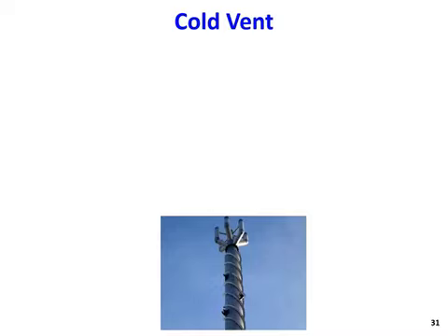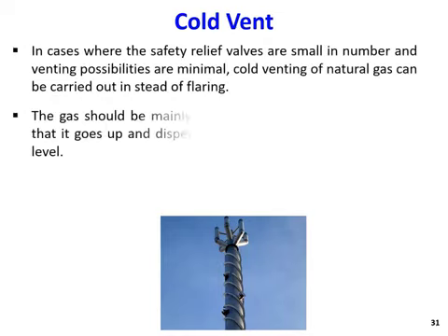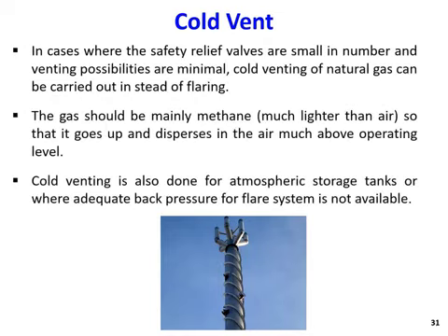So cold vent, as I already explained, can be used in cases where we don't need to burn the vent gas. I mean, in the flare, we don't need to burn it. We can just release it as it is. So in that case, we don't have a flame.